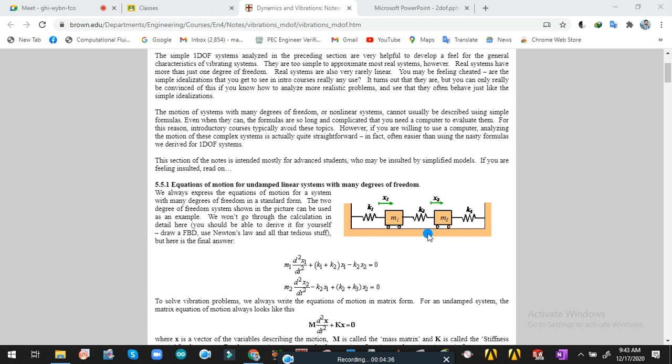So, this is what is expected, how to solve complex systems, because a complex system consists of various masses and various possible types of motion linked with them. So, we need to solve the whole system, and also the mode shape of one component of the system will be affecting the mode shape of others as well. So it depends upon the excitation frequency which mode shape it is approaching.